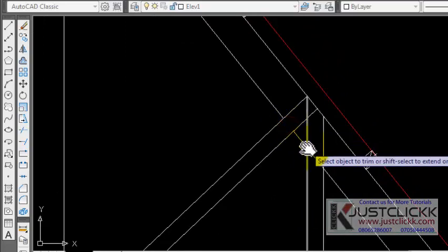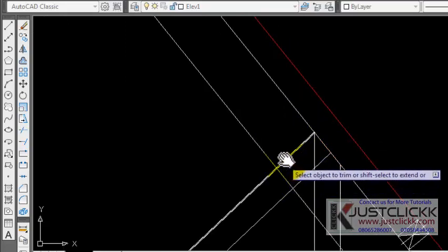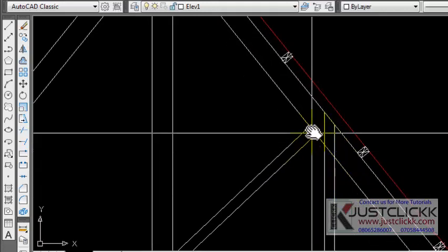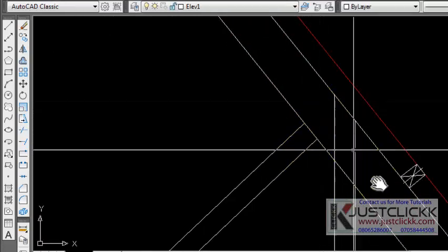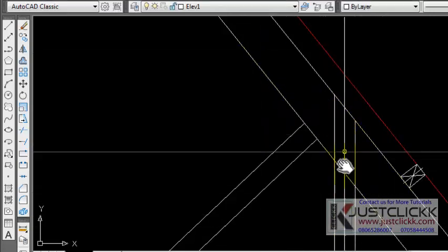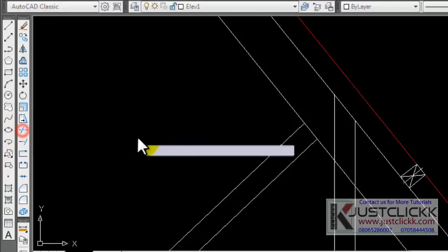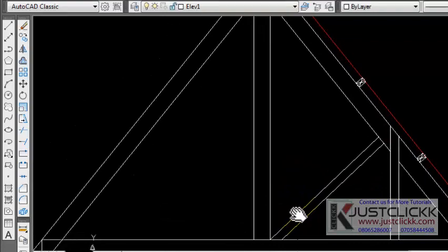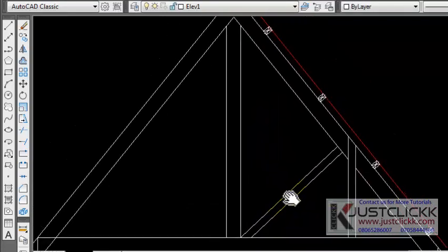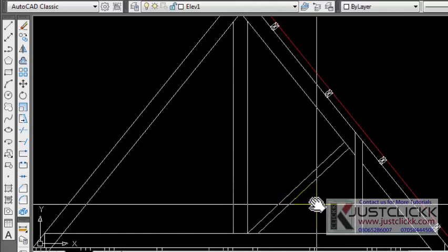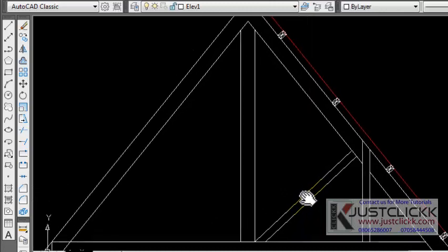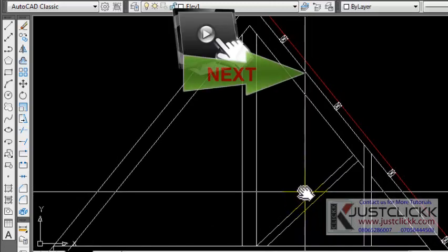Trim this. No, sorry, undo. We don't have to trim this, rather. Yeah, because it's tying to the rafter, so you don't have to see this portion of it. The rafter goes across and this goes across here, so we'll have to trim this as well. Exactly. So that's how you can connect your trusses to the rafter at 1/200. So in the next tutorial we should be mirroring this truss.